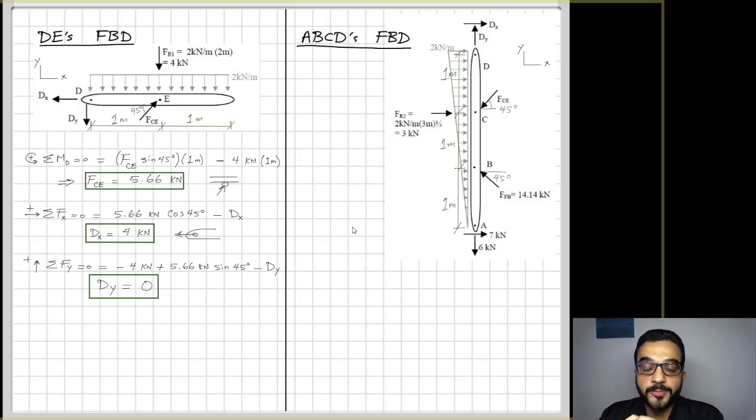So actually I could replace the connection D here with, instead of a hinge, a roller, just having this overhang resting on the vertical member. Is it good advice? No, I don't think so. It's always better to have these connections hinged. Who knows? Maybe there will be a force pushing the overhang horizontally.